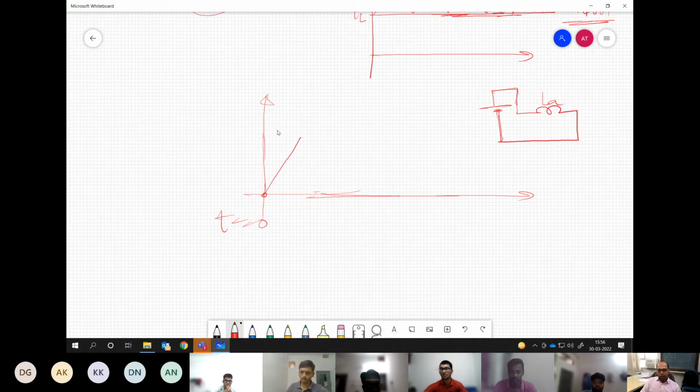Now in your controller, you have fixed a certain upper limit. When this current is rising, you have the complete, continuous feedback of this current, and some upper boundary beyond which it cannot go. The moment it touches the upper boundary, you switch the circuit to the next mode, which is turning on the bottom switch of the half H bridge, and it becomes like this.